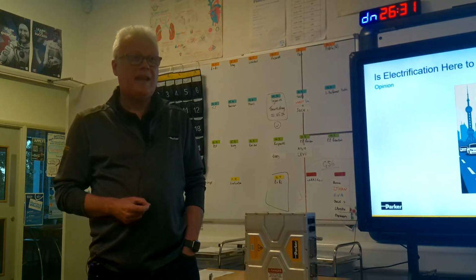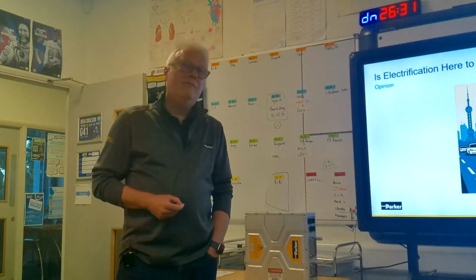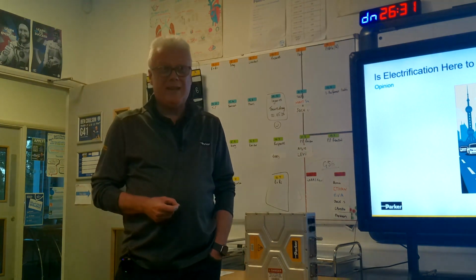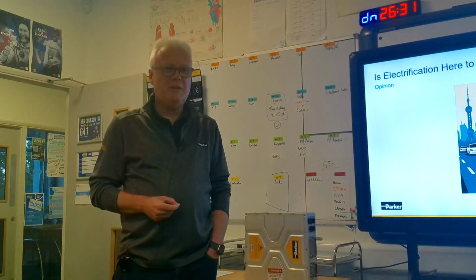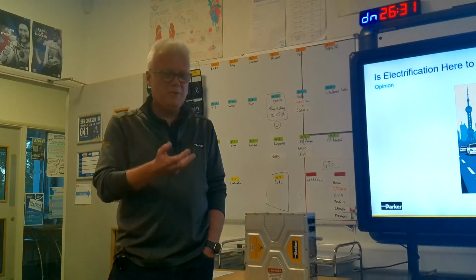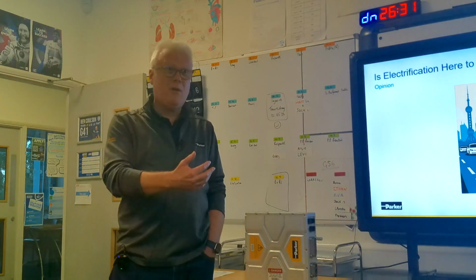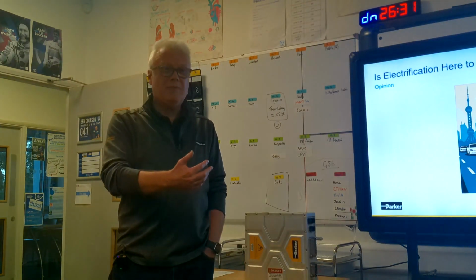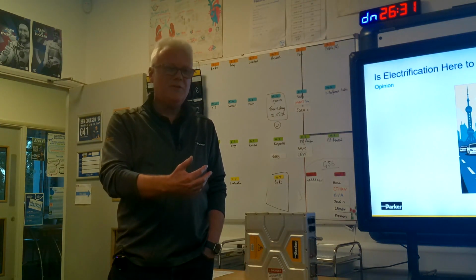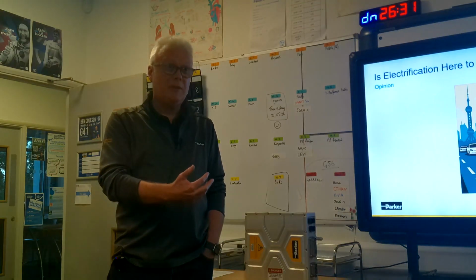That kind of sets the limit. What's the typical slowest to fastest? It depends on how many pole pairs your machine has. If you've got a machine with a very low pole count, 2 poles, 1 pole pair, then you don't need a very high output frequency to support a high speed. It's one of the bugbears of having lots and lots of poles in your machine: to get any decent speed, you need a really high output frequency.